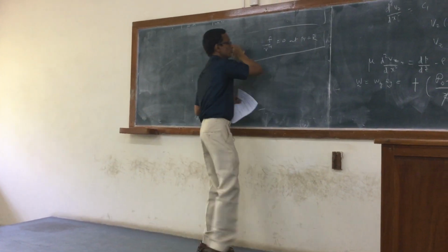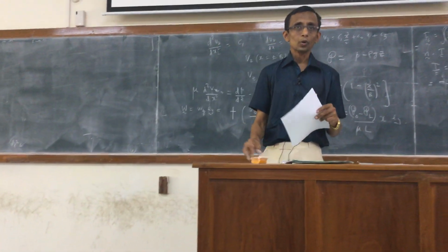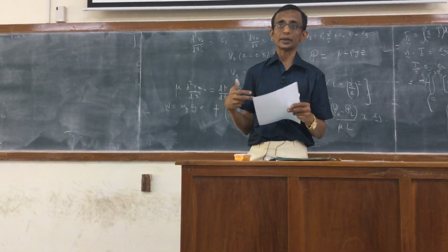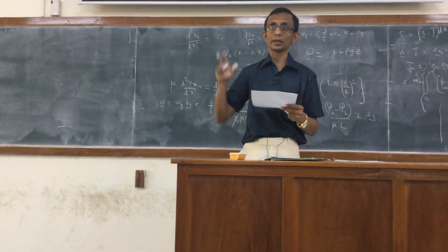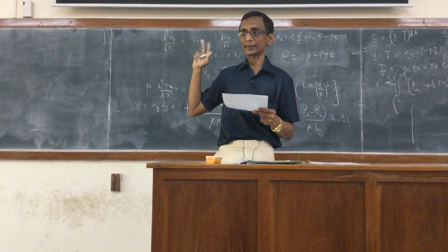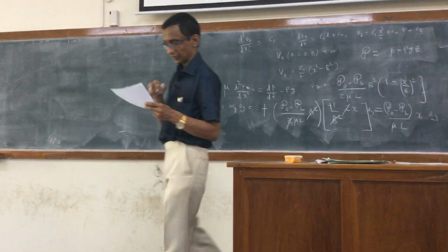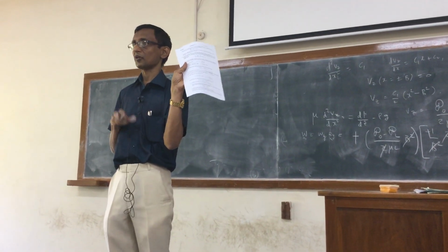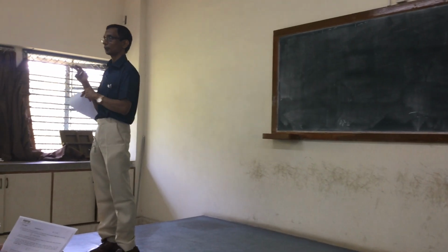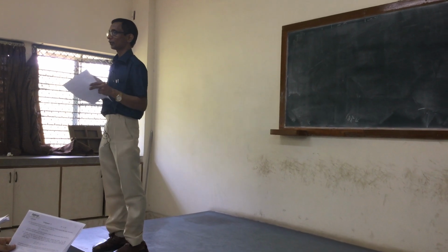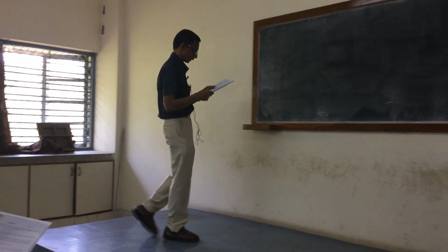Expression for the force is also given. So you have to go through the whole procedure of applying the correct boundary condition, calculating the constants, right? And then the infinity boundary condition remains as it is. I haven't written here the r going to infinity. That you have to retain as it is. The V infinity comes in the expression. Everything remains the same except one of the boundary conditions. The Vθ at the surface vanishing is being replaced by this new boundary condition. You have to get the new velocity profiles and calculate the expressions for the force and verify.